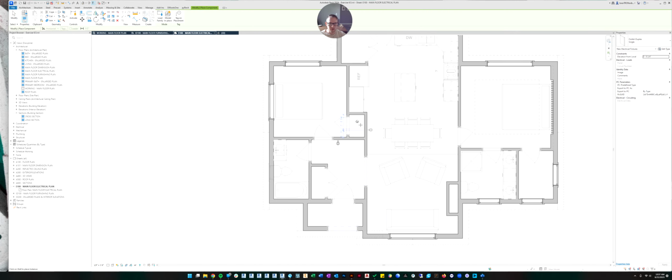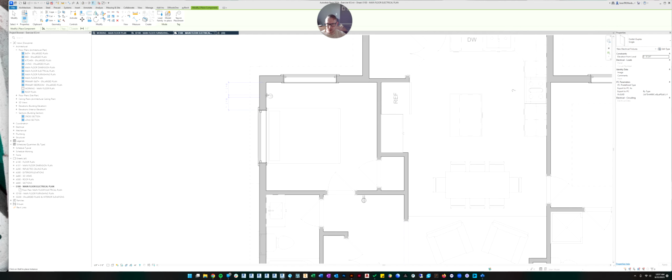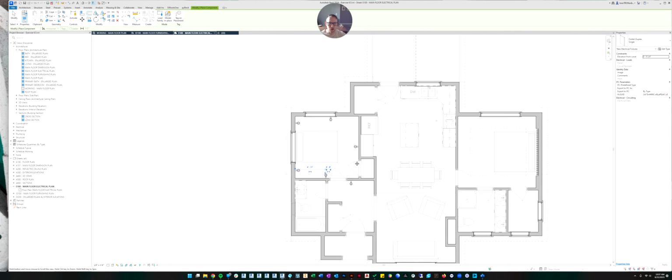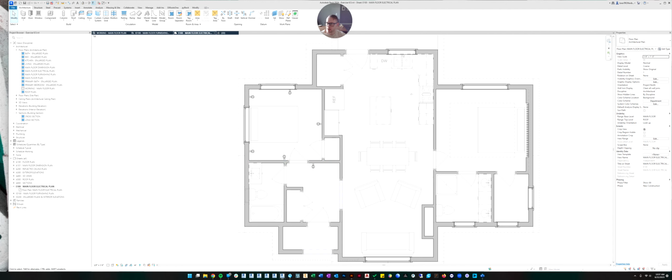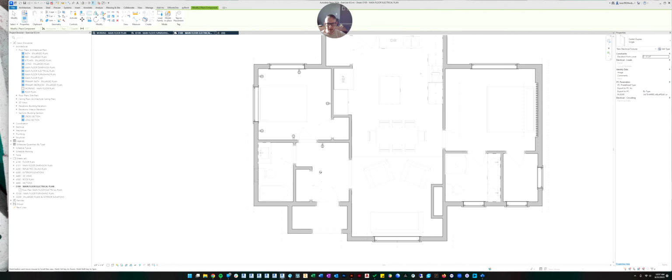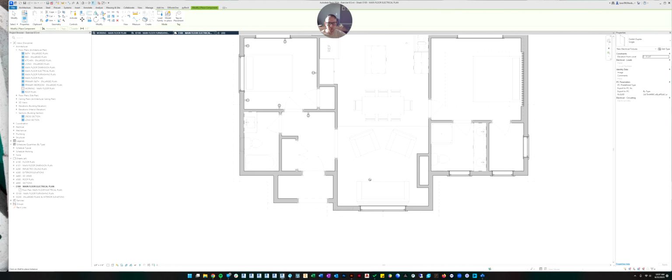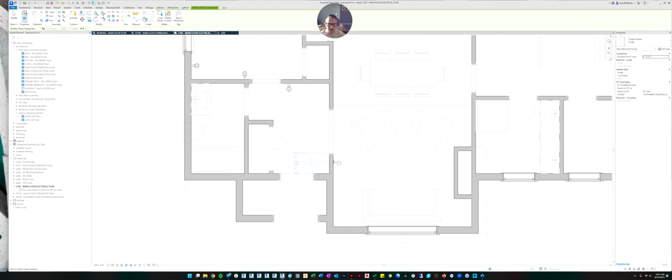So we're still in our single duplex outlet, and I'm just going to put one on either side for maybe nightstand lamps or for charging your phone, and then one on each wall. Now there's codes that have to do with where you place electrical outlets that if you're an architect or an interior designer, you will need to follow. But generally, if you keep them no further than 12 feet apart in most rooms is usually the standard.